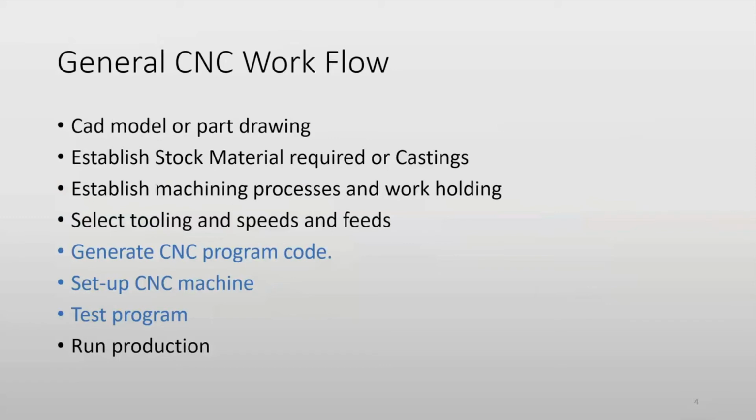Why is the material important? Because each material has different properties, and that property will impact how much pressure I can put on the machine to make sure my tool doesn't break, my machine doesn't break, and also the workpiece doesn't break as well. Then once I've done that, I have to put the workpiece and hold it in place. This is where we talk about the geometry. We define the geometry, right? And we define the block of material, the bounding block, to make sure how much raw material I have. This is something that in the CNC machine you define.